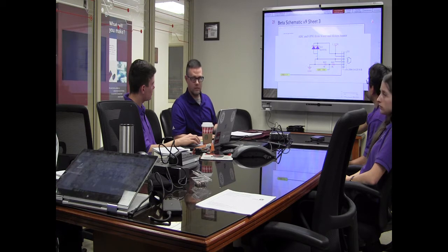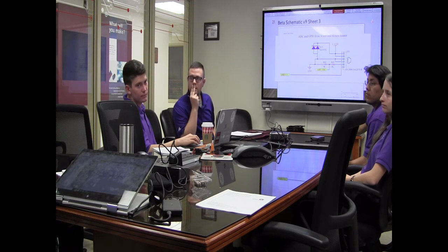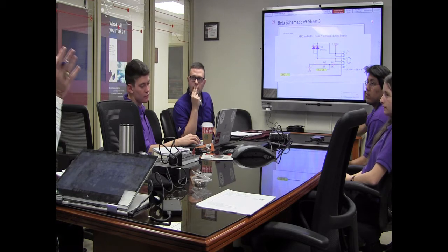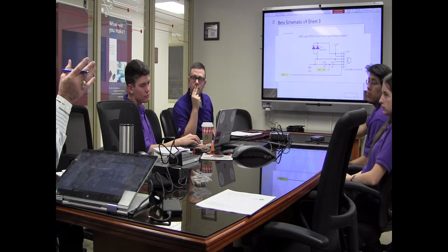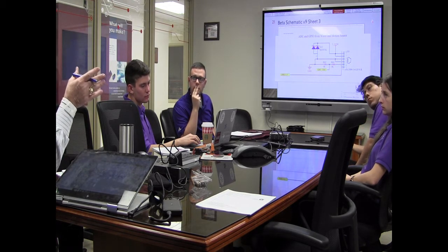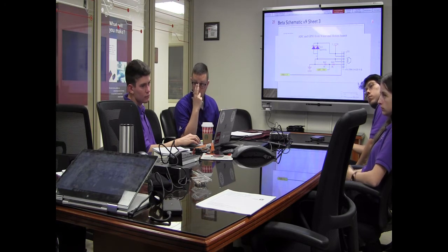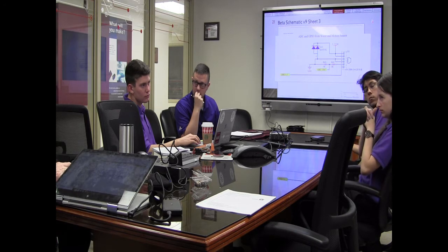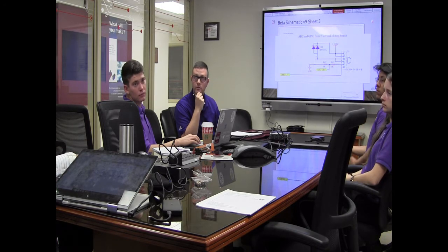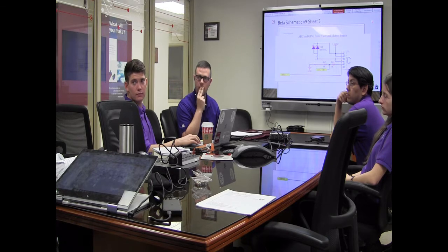RJ12 6. So this has nothing to do with the low side switch. No. And there was no requirement to be able to do that. We just have to remember, if we are going to control some kind of inductive load, that we're going to have to put protection diodes. And they should be, my understanding, as close to the load as possible. That's usually the best. As close to the load as possible, so bridging the 2 connectors on a motor. So we'll put them at the device side. Yeah. Makes sense.